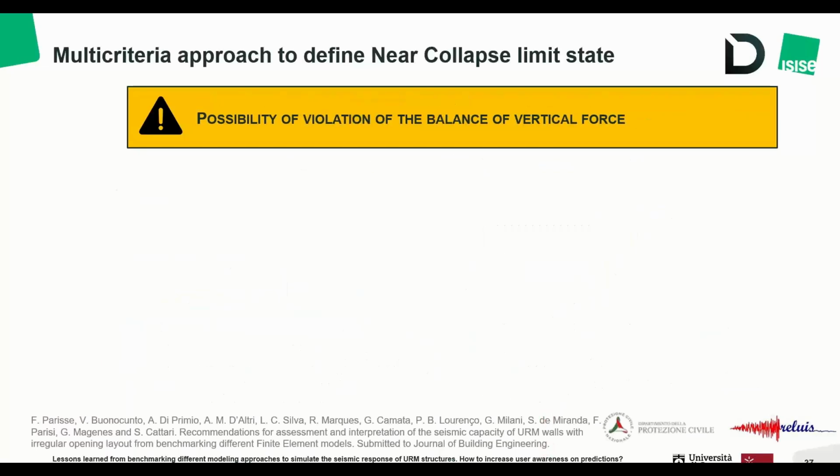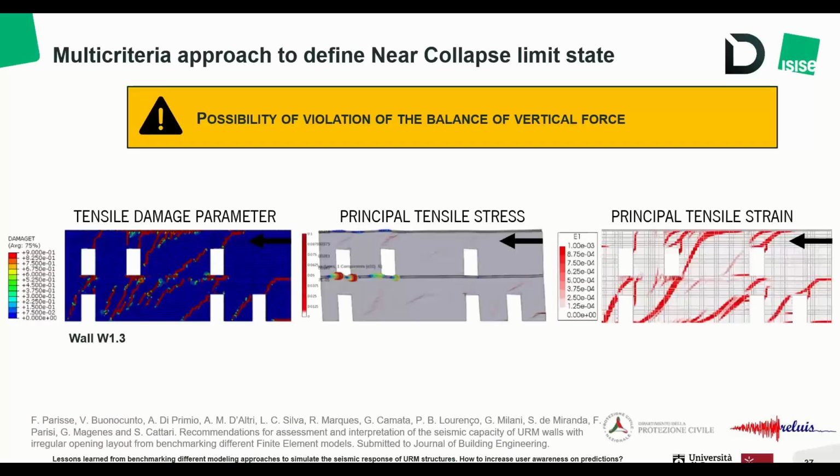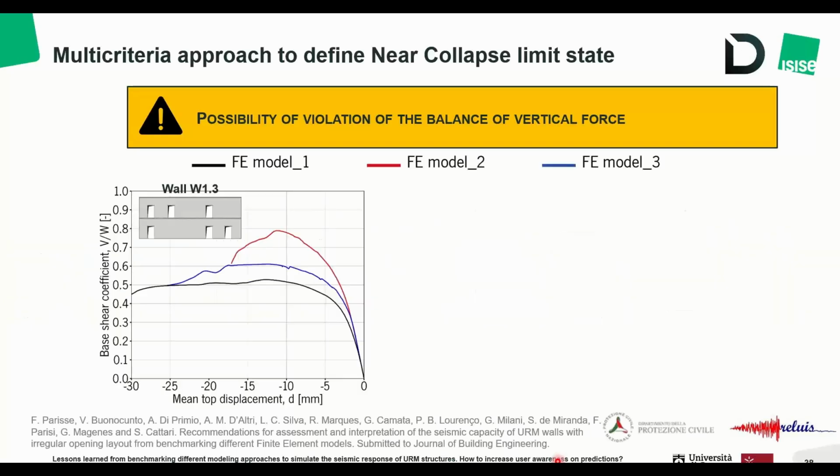Moreover, during the analysis, we also found out that there could be some violation of the balance of vertical forces. Although again, the damage pattern predicted by the different models is quite consistent between the finite element models that were considered in the project, still the pushover curves can be different, as you can see from the graph.